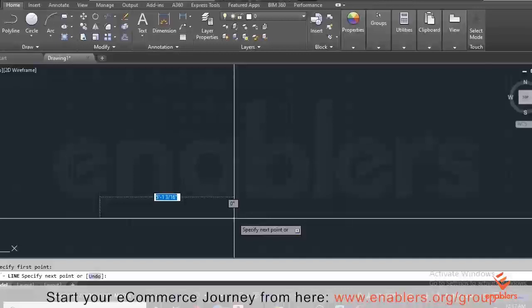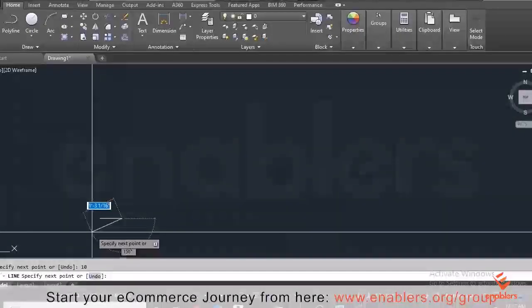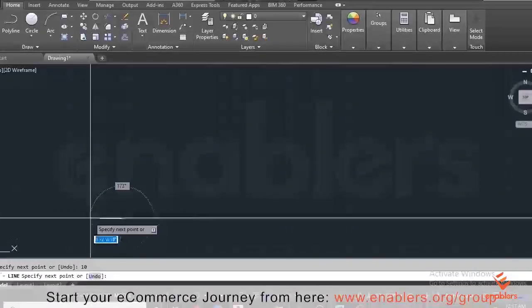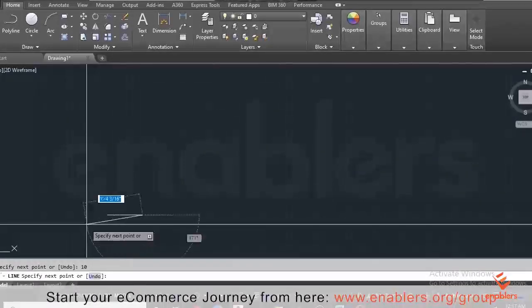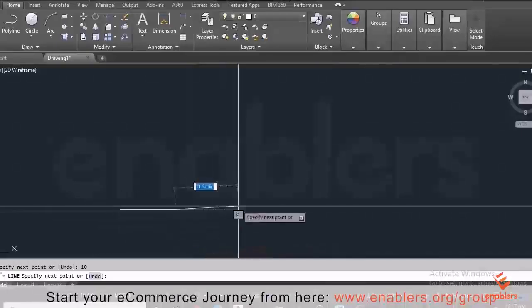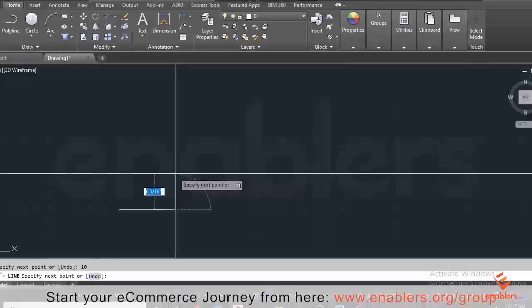When you do that, AutoCAD will show you the bar on which you will see the approximate length of the line. Let's make a line of 10 inches. So I am going to type 10 and press enter. And we will have a line of length 10 inches, which is pretty tiny here. So let's zoom in. Now I will move it to the top and then I will type 5 and enter.